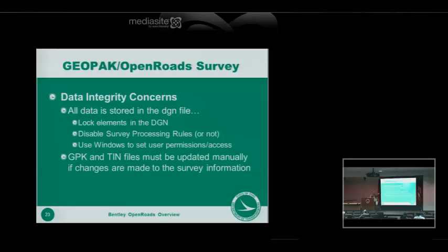So in your case, if you'd surveyed on the grid, and you converted it to ground and brought in ground coordinates, well, what you could do is survey on the grid, bring it in on the grid, and assign it Ohio North, NAD 83 or whatever. And then it knows that's where it lives. And then if you make the custom, then you'd go pick the custom one, and it would transition it to ground coordinates.